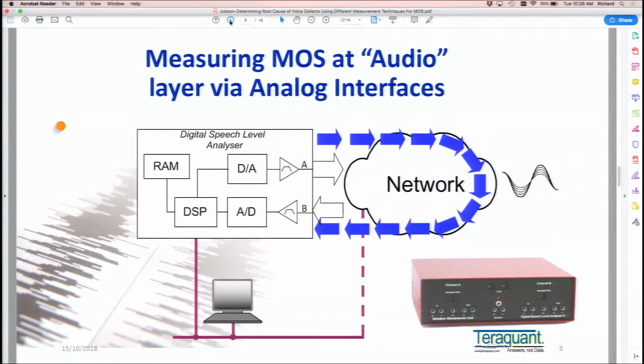So just what we're doing here, in contrast to the sniffer and Wireshark, where we're passively monitoring in a number of different places, with an audio level measurement we're actually generating some audio out of these analog interfaces, putting them into your analog interface, which might be the coily lead off your telephone stuck in there. It might be this interface right here I have plugged into my computer so I can test the software.